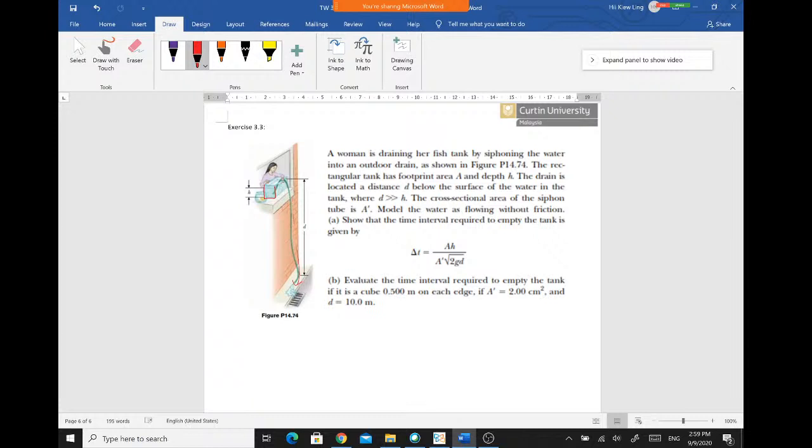First of all, you must create a vacuum in your pipe here. Because of the difference in pressure, the water will be pushed by the atmospheric pressure to go into the pipe, and it will continuously pump all the water from the first container until the container is empty.